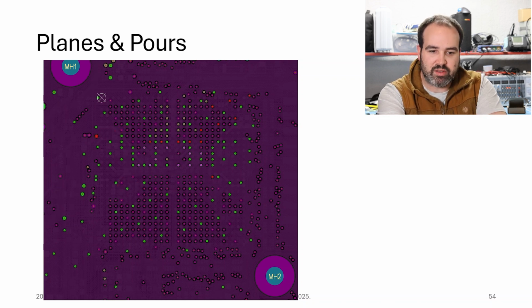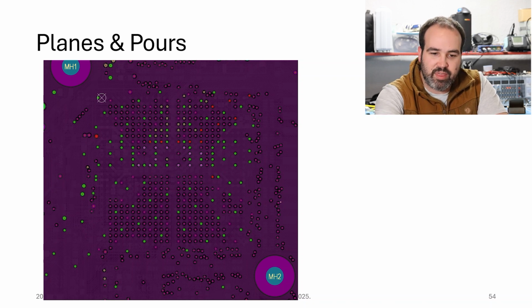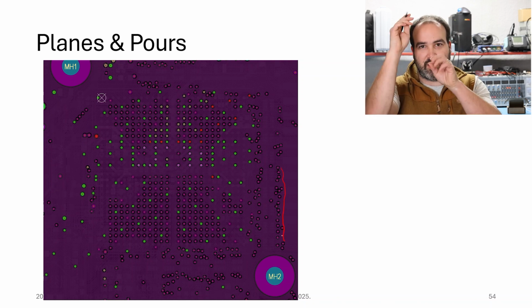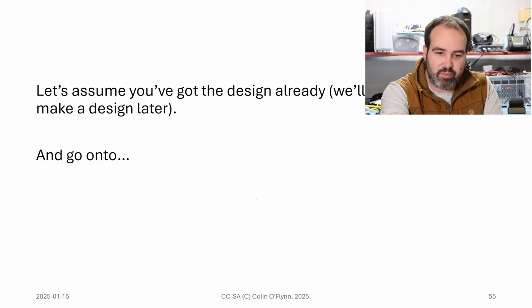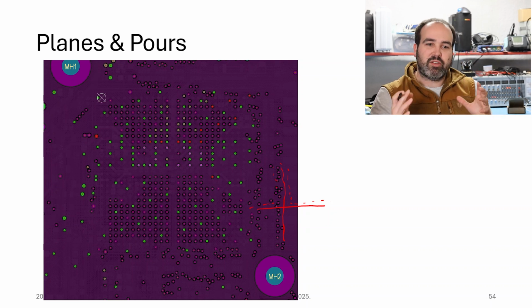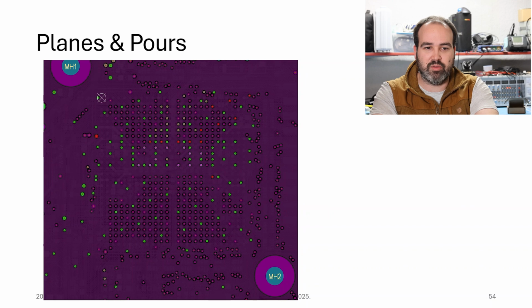I bring this picture up because one other thing you can run into if you do a ground plane, if you're doing a 4-layer board, is that it's not just magic. If you look here, you'll notice that these vias are not connected to the ground plane, and they actually make a section where the plane could be fully broken. If I'm not careful, I could make a pretty big break in the plane if I stack my vias up, right? And so this means that if I cross a plane, I now get back into this big loop because it would have to go all the way around that. So if you're using a plane, watch out for the vias. If you have the density that's too high, you can actually puncture your plane. So that's something else to watch out for with using them.